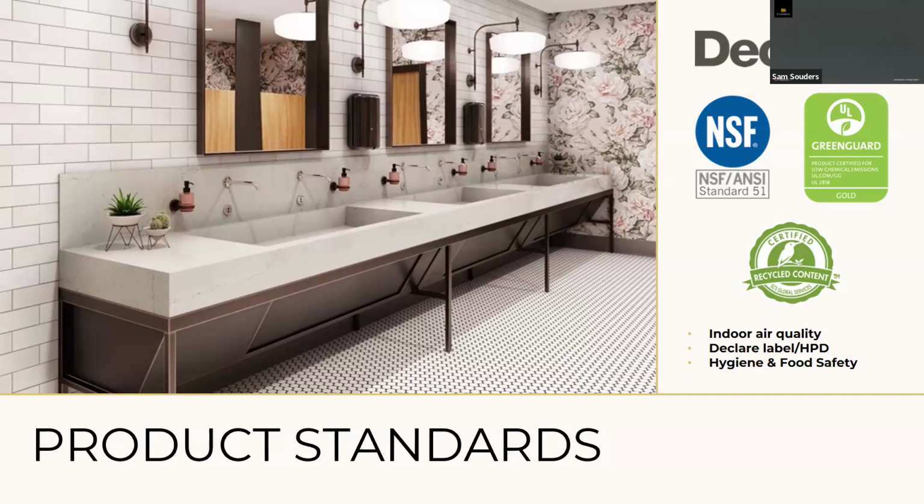LEED. In addition to most leading quartz surface products meeting indoor air quality standards for LEED, these products may contribute points to LEED certified buildings in the indoor environmental quality category and/or the materials and resources category of various LEED green building rating systems. These are considered low emitting materials that can be reused, recycled, with some manufacturers sourcing and extracting raw materials in a responsible manner.